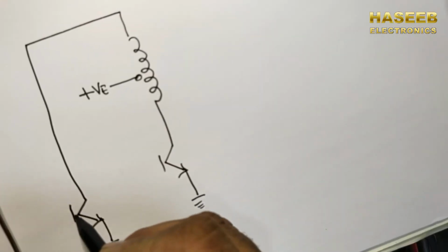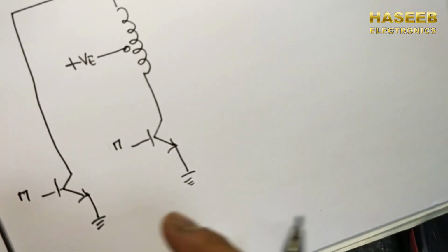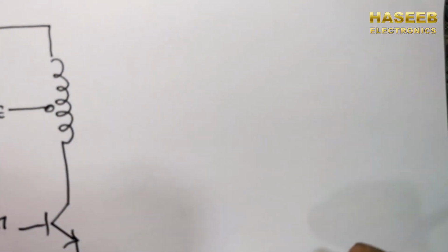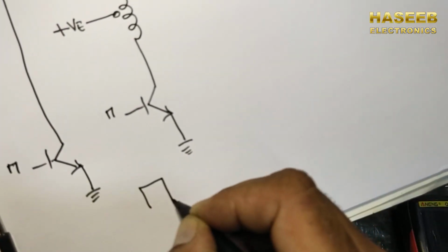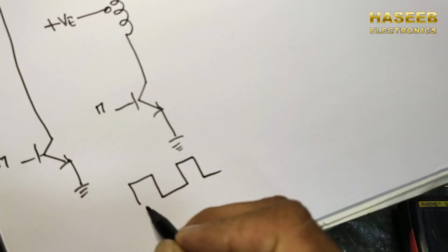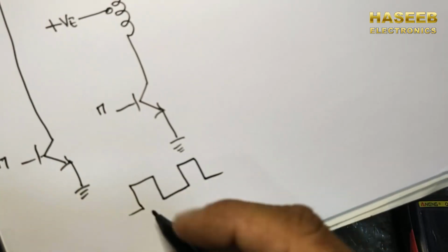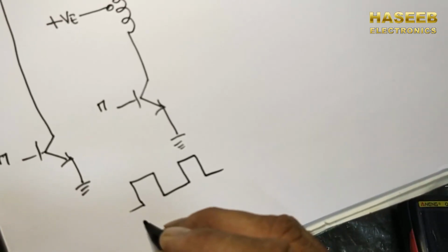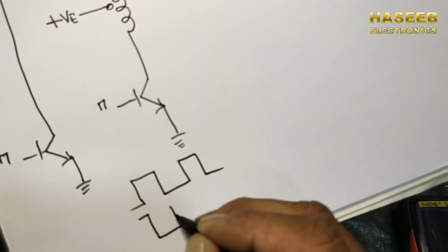We have one signal here, either it is a MOSFET, IGBT, anything. In the ideal case, we say it is generating a square wave. So in case of a square wave, the ideal signal, when it is applied to the base, goes high, and the output must be similarly high. But no, in practical life there is a big difference between this theory and practical circuits.